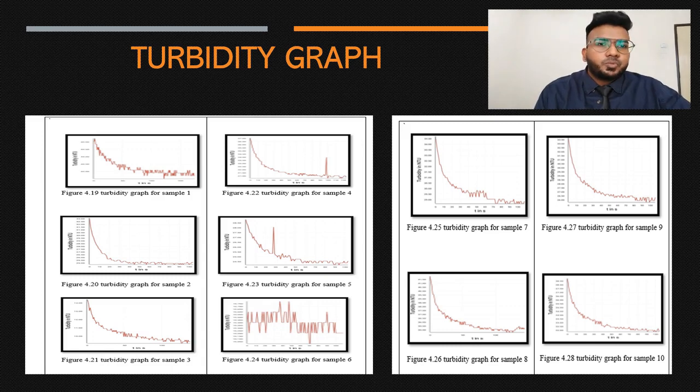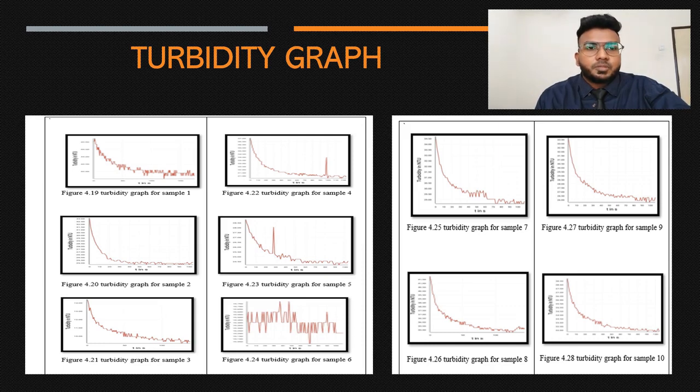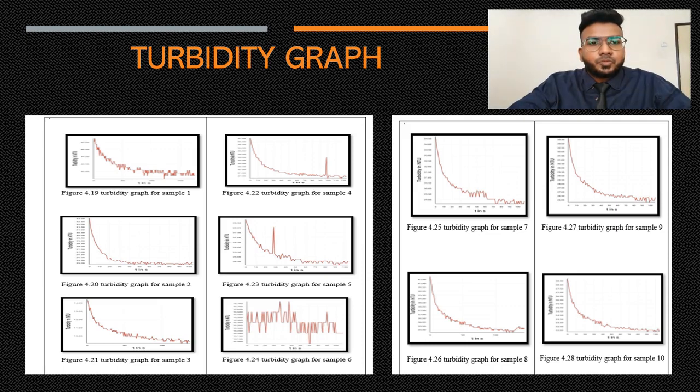The turbidity value of the flood water tested is 130 NTU. However, the filtered water shows a lower NTU turbidity value compared to the original collected water sample. The highest turbidity value obtained from the testing is 43.26 and the lowest is 10.30 NTU.